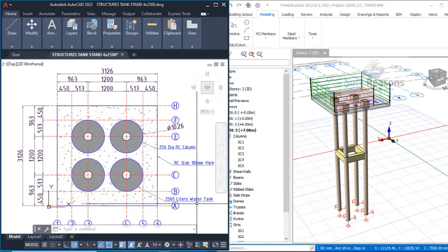The unit weight of water is in kilonewton per cubic meter. By the time you multiply it by the height of the tank, which is in meters, you have kilonewton per square meter, which is an area load we will be applying on this structure. That is the simplest way to get that. The other, longer methods you can check in my videos; there are other ways to calculate that, which I did on this channel.